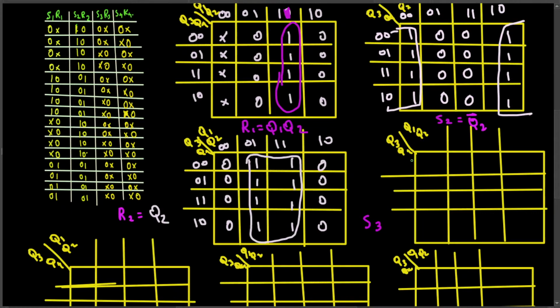Let's put the truth table we derived. It is 0 0 don't care, repeated all the way down. For this one there are two possible answers. One is, if you don't see any ones, you can directly connect to the ground. You can put it as 0.